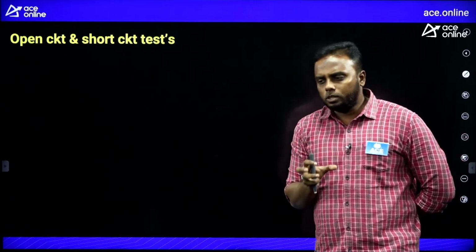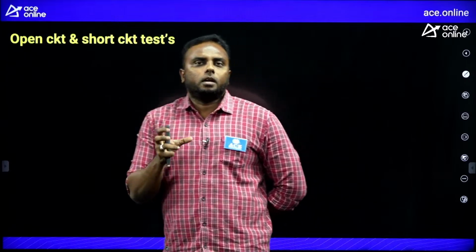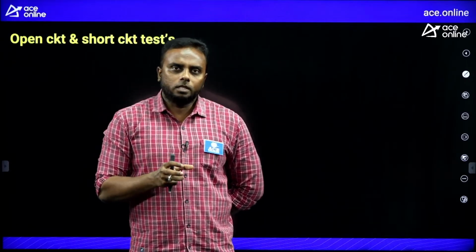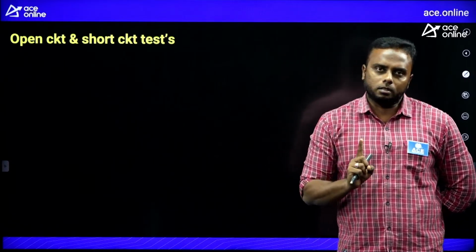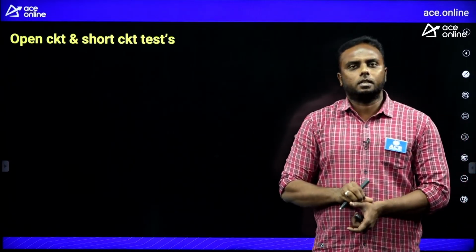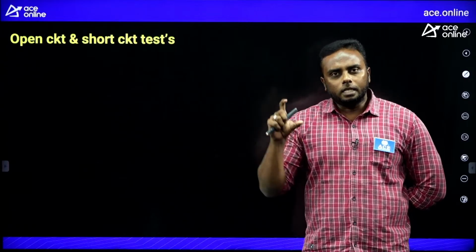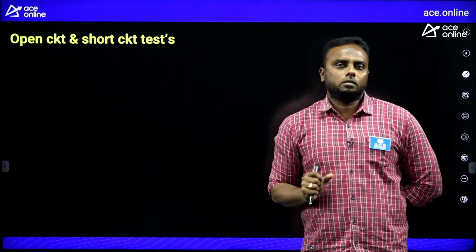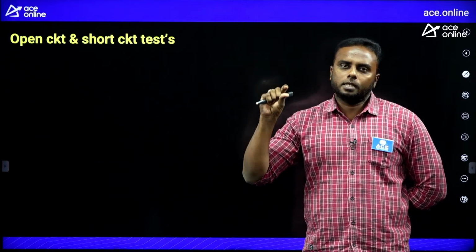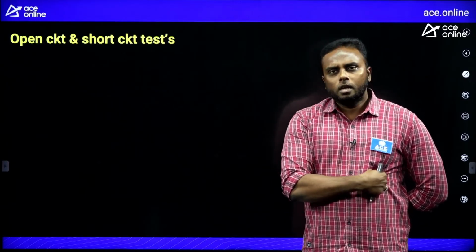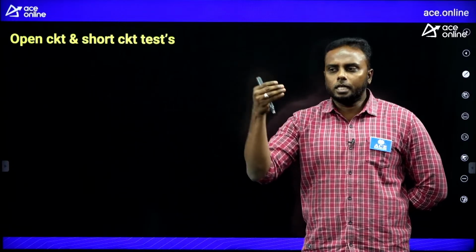So what are the objectives of the OC test? The main purpose is to find iron loss, or core loss, or constant loss, to find the shunt branch parameters R0, X0, and third, to separate iron loss into hysteresis and eddy current loss. So you should know all these procedures whenever they give some OC data.